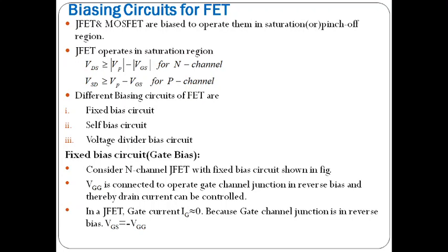We know, like BJT, the parameters of FET are also temperature dependent. In FET, as temperature increases, drain resistance also increases, reducing the drain current. So, due to this, thermal runaway does not occur in the FET.